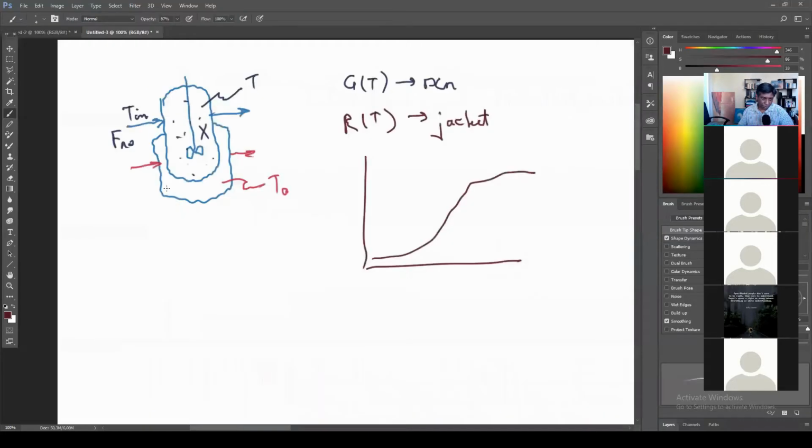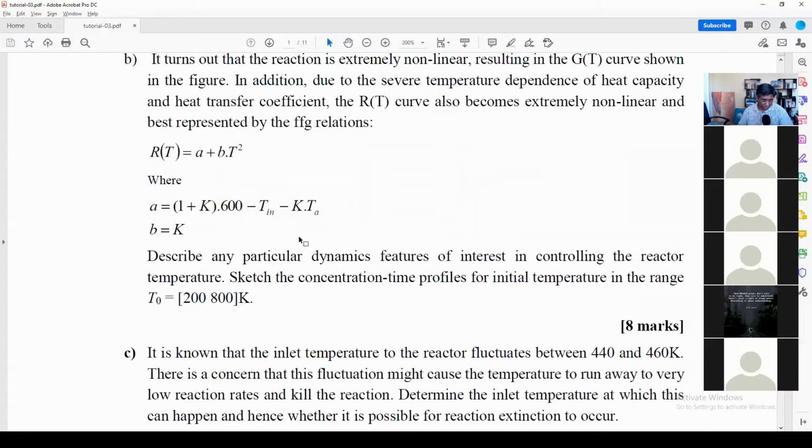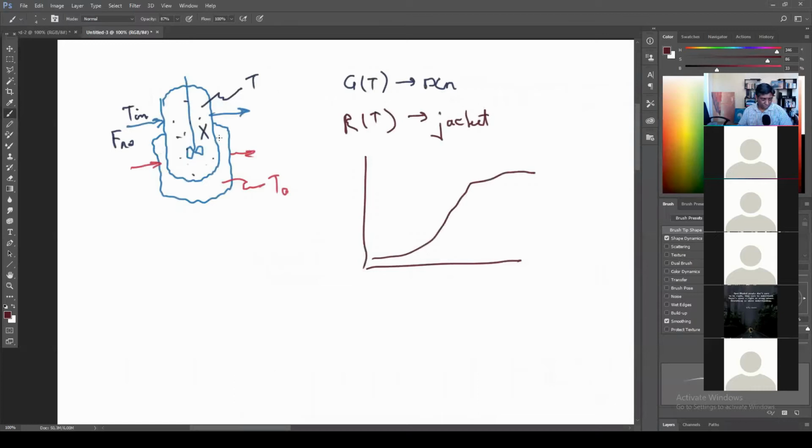So if you look at our picture here, we've got the inlet temperature to the reactor. So this we consider as being something external to the heat transfer that's going on there. So in terms of your inlet flow to the reactor, that we consider to be under the control of upstream processes and maybe some other control and things like that. So we are not really thinking about changing T in. So we regard that as a kind of constant. So that's out. And then this TA is more of a concern to us because the temperature you accomplish in this jacket is a function of the temperature in the reactor itself.